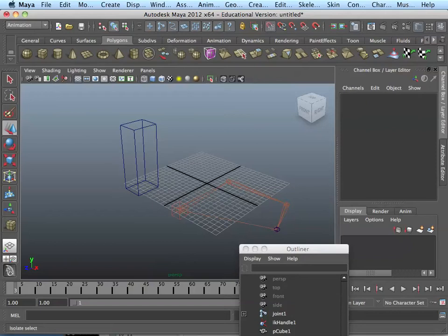But when you start thinking about it, if I ask you on any of these machines how many degrees that servo is moving, you would say about this many, right? But the way you do it, even with the arm on it, is you just pop it through here, set it at 0, set it to 180, and measure it, right? It goes 147 degrees or something like that. So then you know, in my physical world, I have an object that will turn a total of 146 degrees.